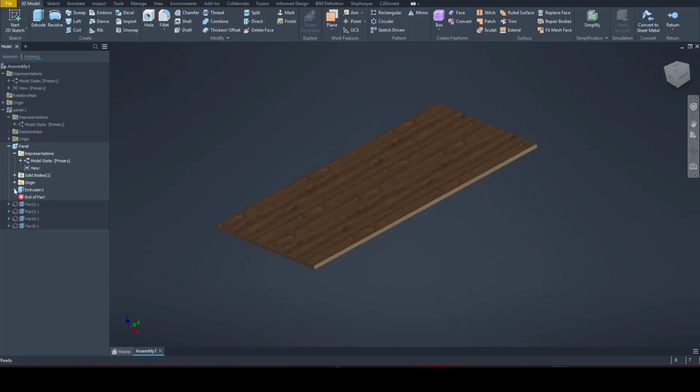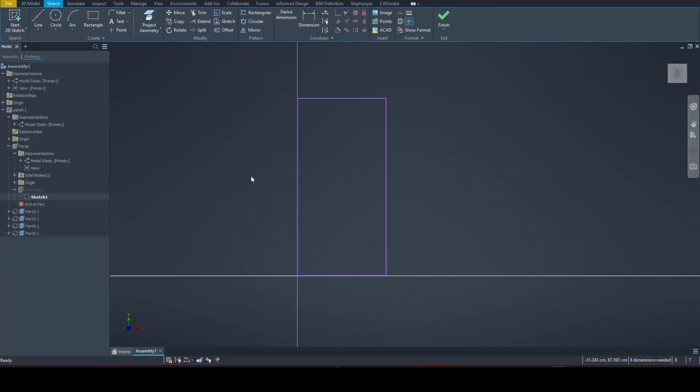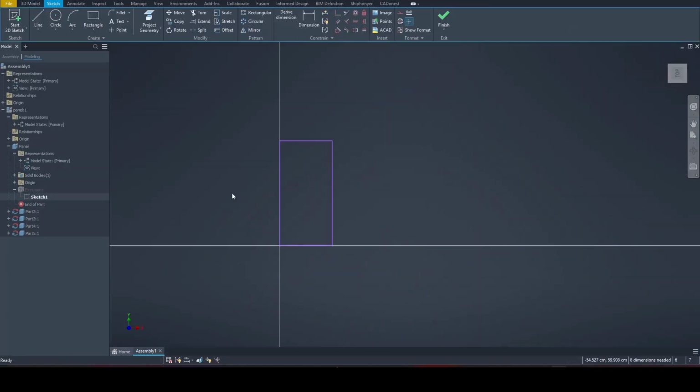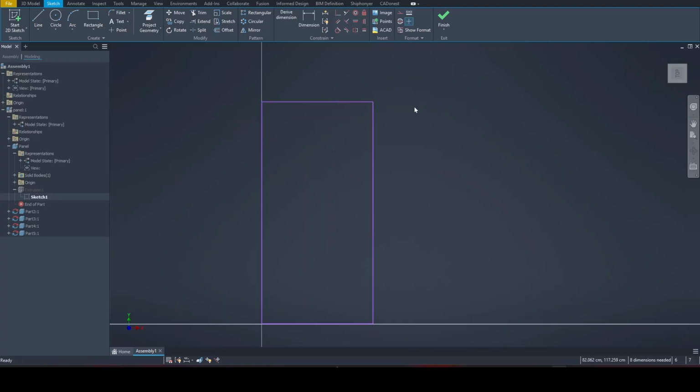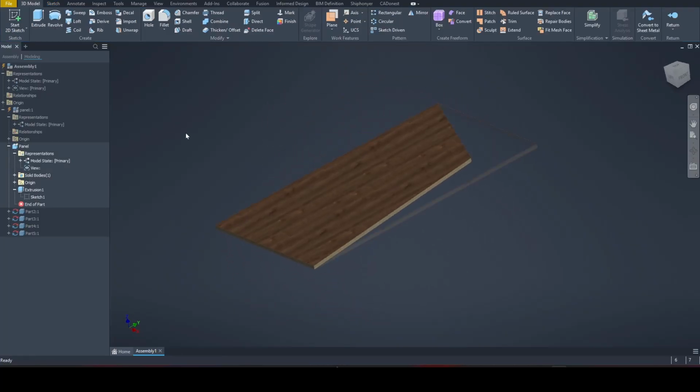The command is designed to create a panel this way, as a rectangle. This purple color indicates that the profile is not fully constrained. It requires 8 dimensions for full geometric definition. And that means the geometry is not fully constrained, allowing you to modify it if needed. And because there are no constraints applied, you can, for example, select an edge and move it inward. If you click Finish and then Update, you will see that the edge bands follow the new shape automatically.